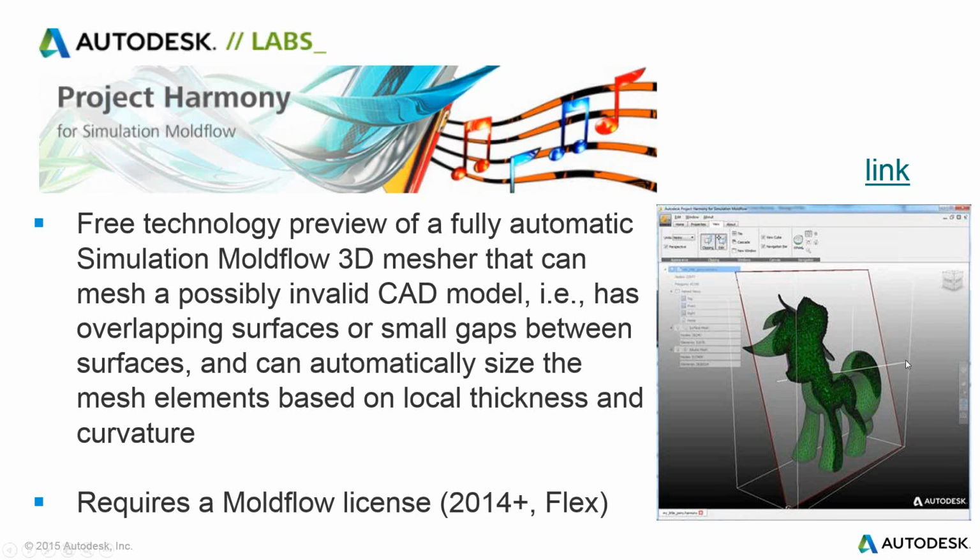It automatically creates a crinkle cut, we call this, of the 3D mesh. Inside the Moldflow interface right now, in order to see the interior of a mesh, you have to move things to a different layer and hide a specific layer, and that is not very intuitive. I think this might be another area where we have some good learnings, to see if we can reapply this back into Moldflow.